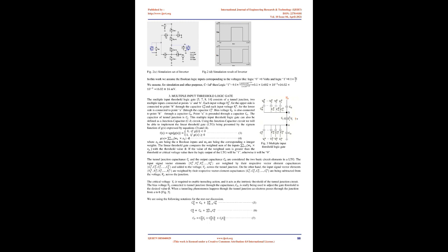The increment of the differential resistance of the tunnel junction around zero bias is called the Coulomb blockade. The principle of single electron technology is developed on the basis of single electron tunneling and Coulomb blockade. Single electron tunneling circuits seem to be promising candidates for future VLSI circuits for their ultra-low power consumption, ultra-small size, reduced node capacitance and rich functionality.